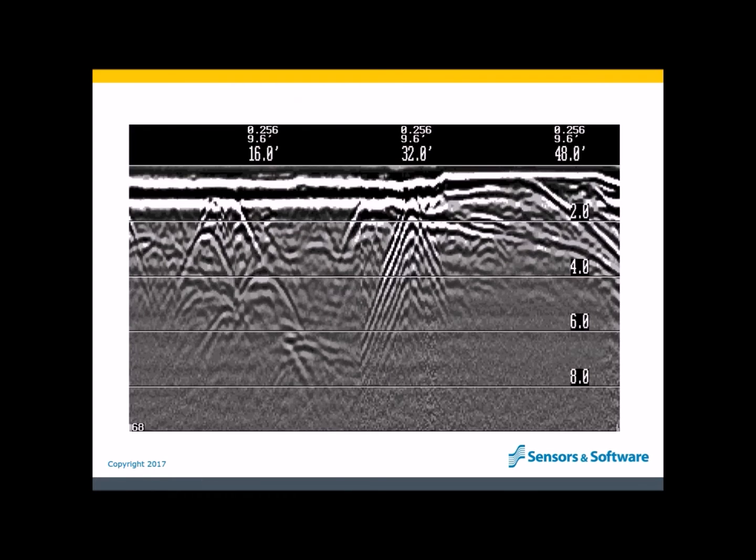Okay, back at this section. So if the bands across the top of any GPR line are the direct arrivals, what happened here? Why does the direct arrival change at this point on the section? You can see that it is different on the whole right side of this GPR line. The answer is that the surface conditions must have changed, and that changed the direct ground wave.